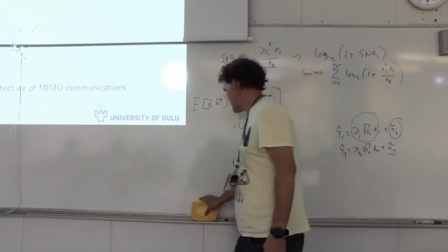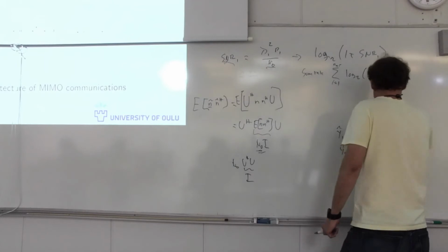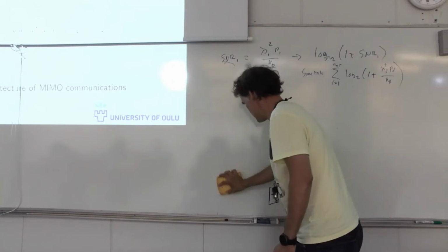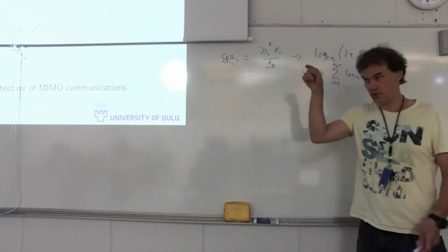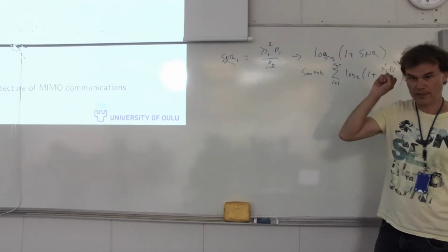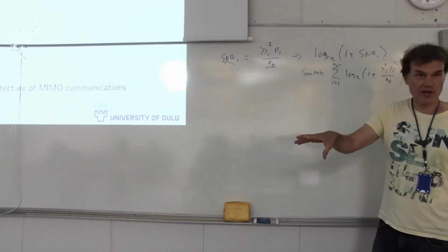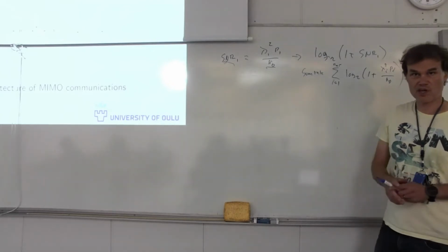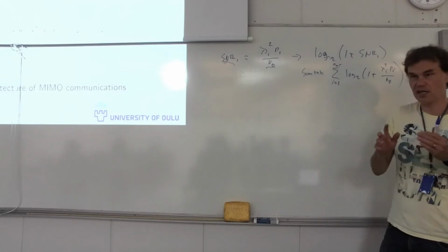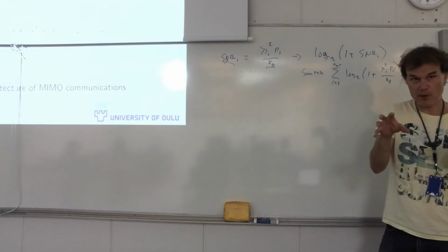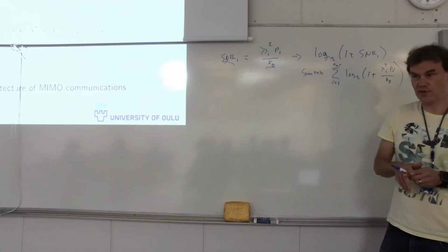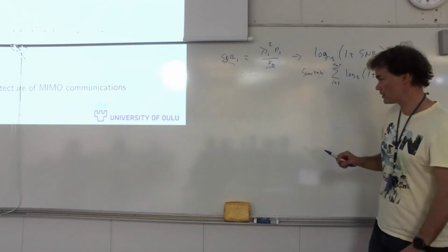Now the question is, if we have a limited power constraint transmitter, and we have a base station serving a single user. It has power amplifiers that have limited transmit power. If we now assume a somewhat unrealistic scenario that there's a power constraint over these power amplifiers, in practice, each power amplifier has its own constraint, so it's the per-antenna power constraint.